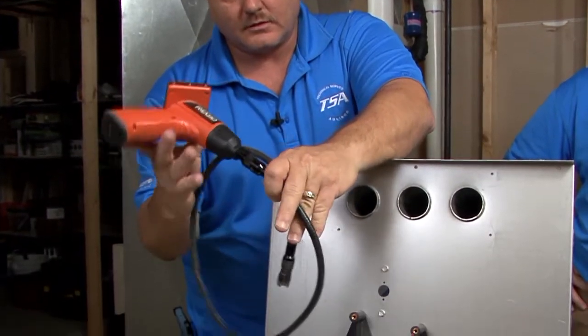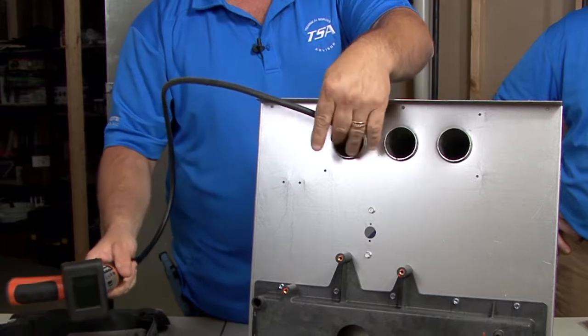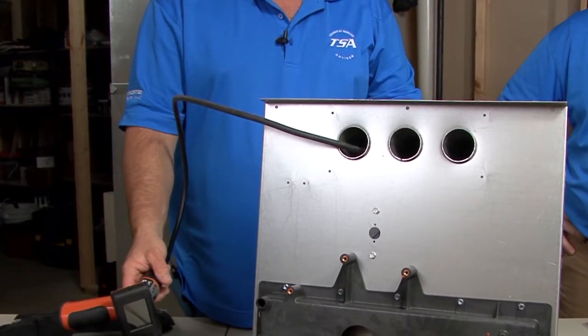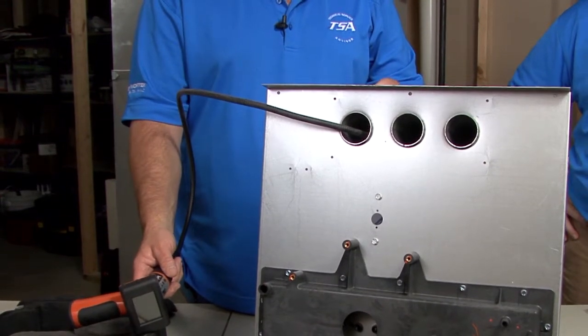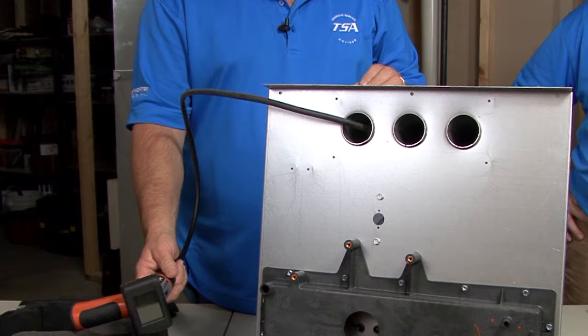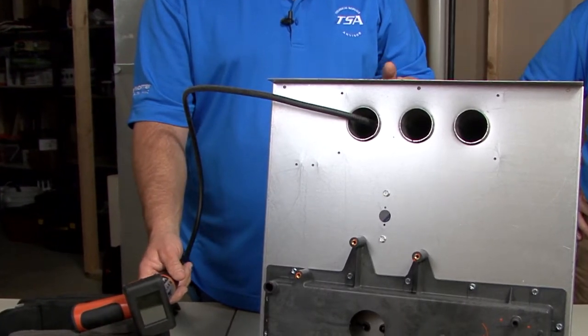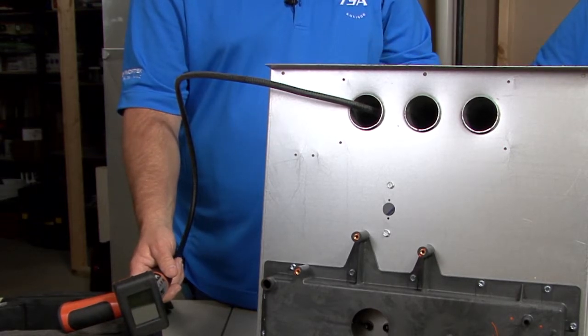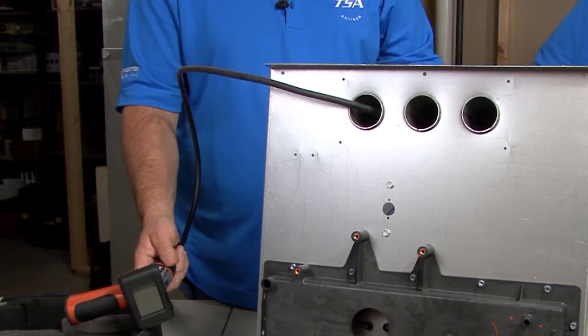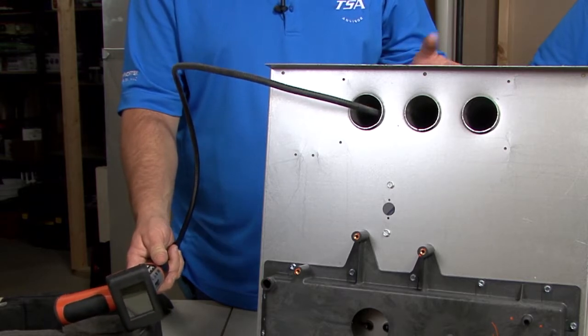So they do have their uses, but for a heat exchanger, no, I don't necessarily think it's the best thing to do. Because the problem with the snake camera is the guy's going to get this thing all powered up, and he's looking at the camera, and he's going to shove this down in here, and he's going to start looking for a breach in the heat exchanger. But the picture's not clear enough that you're going to definitively be able to tell a crack in the heat exchanger, a hole in the heat exchanger, versus just maybe possibly a little rust spot.